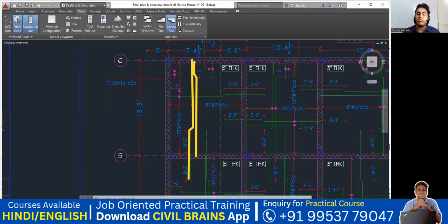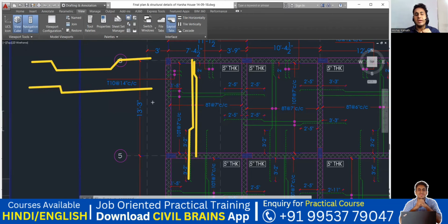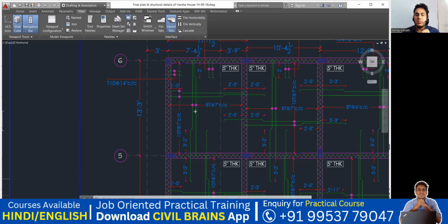So there are different ways of giving a bar. Right now, I taught you both-side crank. This is also crank. This is also crank. Sometimes we give crank on only one side and take it, and then give crank from the other side and bring it in this way. It all depends how the structure consultant has given it. Here what he has given is a straight bar, a crank, and the top will go. Then from here you will get the same bar, you'll give a crank and you'll bring it here. Very simple. Similarly on the other side you have done the same thing.